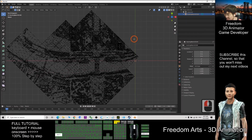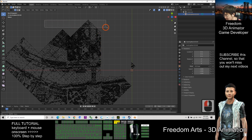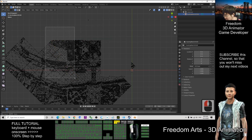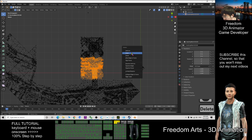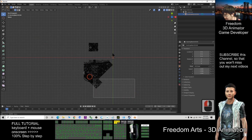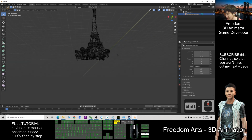Click the Z, hold the Shift, use the middle button, delete the unnecessary part. Delete vertices. We only want to leave the Alpha Tower. Delete vertices. If the rest are unnecessary, delete all the vertices. Here also delete vertices. Now, the Alpha Tower is this one.